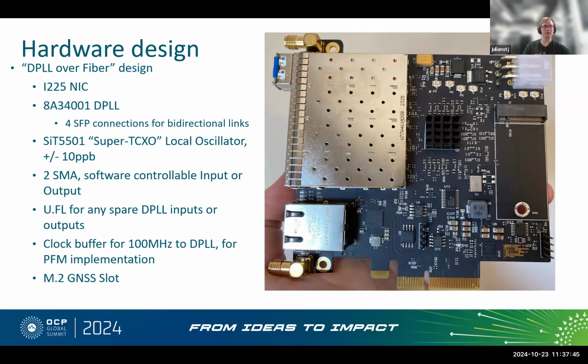I would say they're all kind of boundary clocks because they're taking the signal and then regenerating it out. So they all add to the path delay, path degradation, whatever you want to call it. But the fact that it's all tracked through hardware gives you the precision to get down into the sub-nanosecond range. The reason I built the board with 4 ports was basically that you need 3 ports on a design to get to a network, right? You need an input and then at least 2 outputs. And I figured I might as well do one more.